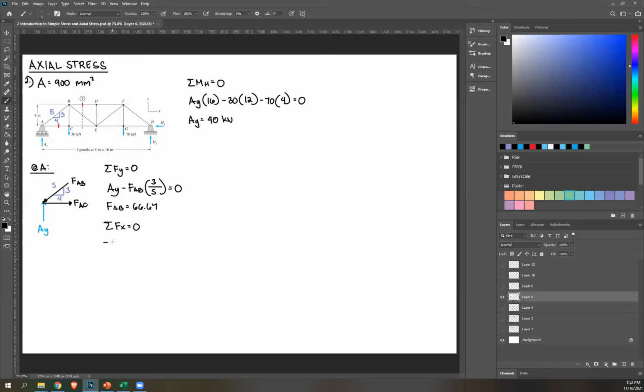Let's start with FAB. That's to the left, so negative FAB. To get its horizontal component, copy the horizontal side. So 4 over hypotenuse 5. FAC to the right, so positive FAC. Considering AB is this, please solve what's FAC.